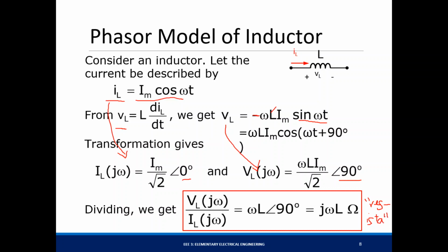So yeah, you get the point. I can't write that; it's so long and we have no more space. Anyway, it's kind of a resistance when we map this phasor value from our time domain expression. This inductor kind of becomes a resistor when you map it into its phasor form, with its resistance being complex: j omega L. Omega is the frequency of the function, L being the inductance.